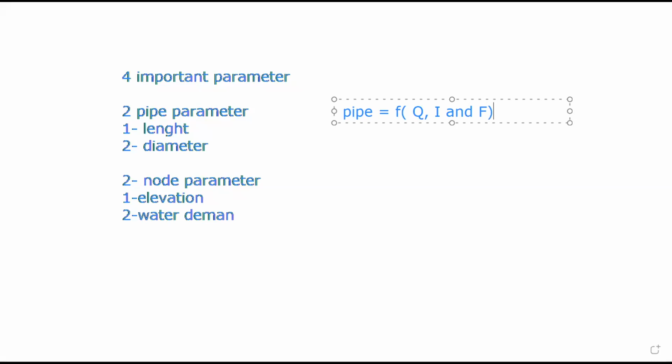These are the factors. So for you to get the pipe diameter, you need the slope of the area, or the flow between the beginning and the end of the pipe. You need the frictional factor, the frictional material of the medium of conveyance, or the frictional factor of the pipe, or of the channel. Assuming you are doing runoff, you need the frictional factor. That's what we call the Manning's n.